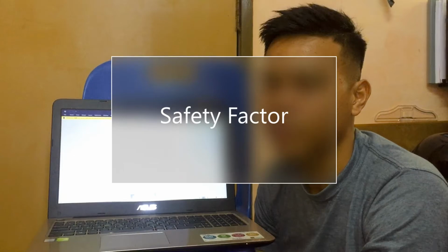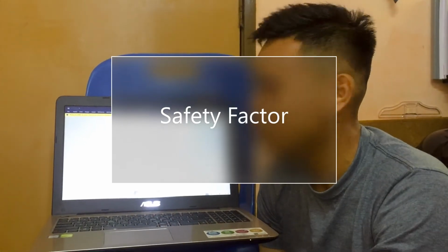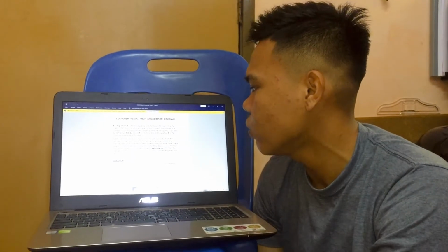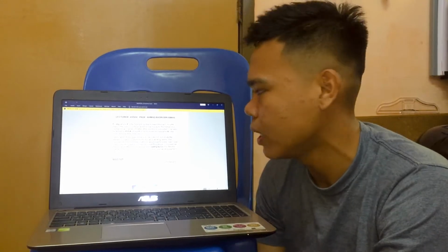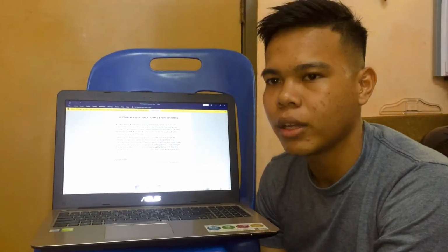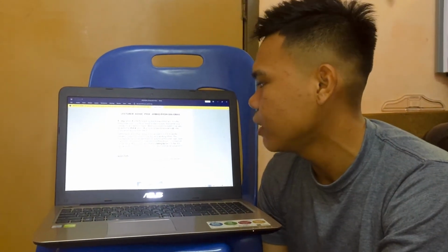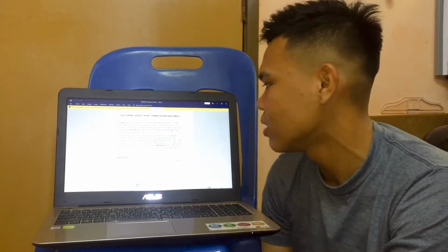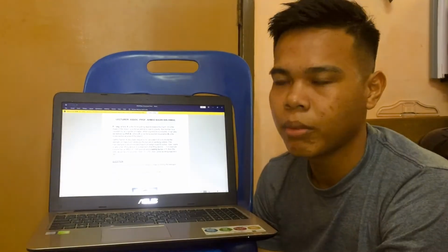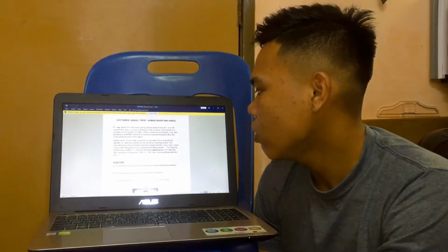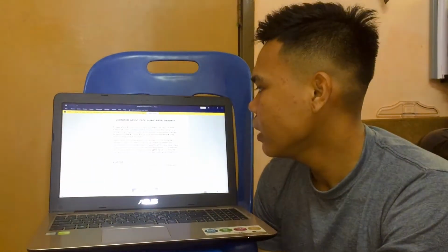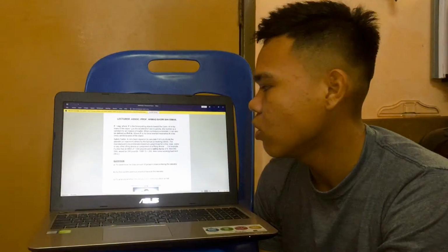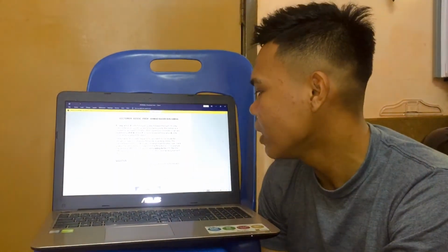I will tell you about the safety factor. The safety factor is a very basic equation to calculate the factor of safety. It is to divide the ultimate or maximum stress by the typical, or what we call the maximum working stress. The manufacturer recommended maximum weight load for a line, rope, crane, or any other lifting device or component of a lifting device.